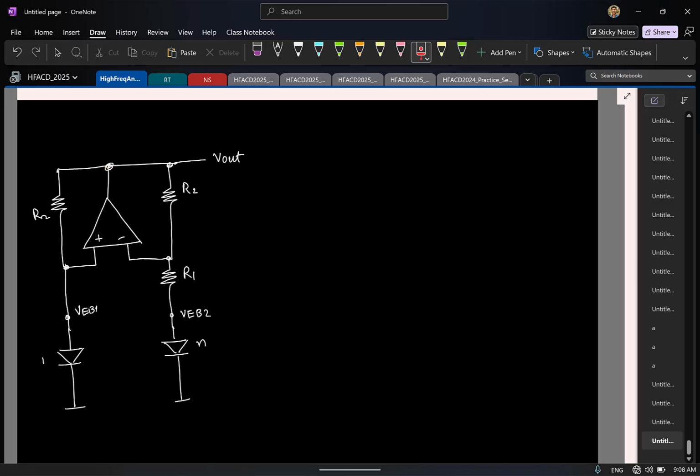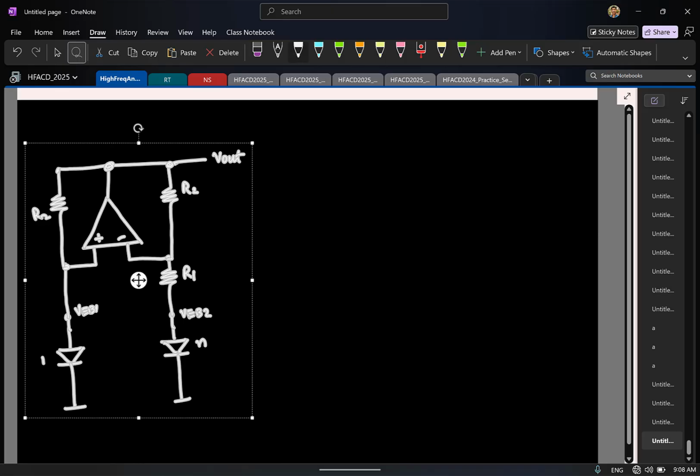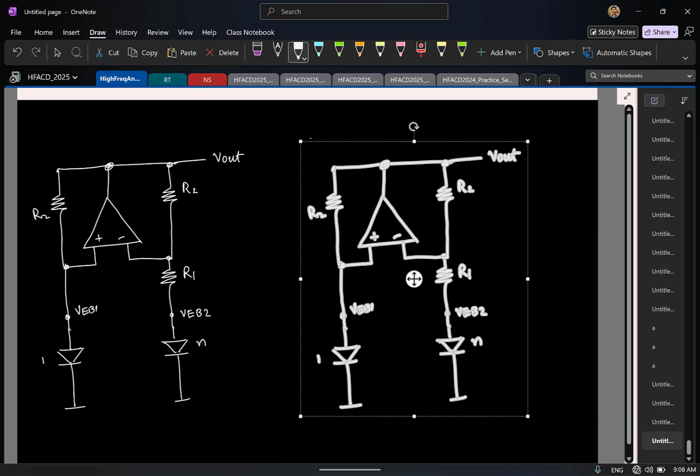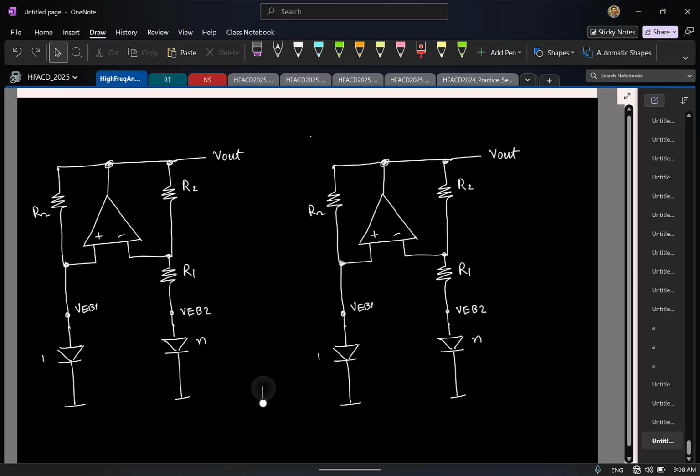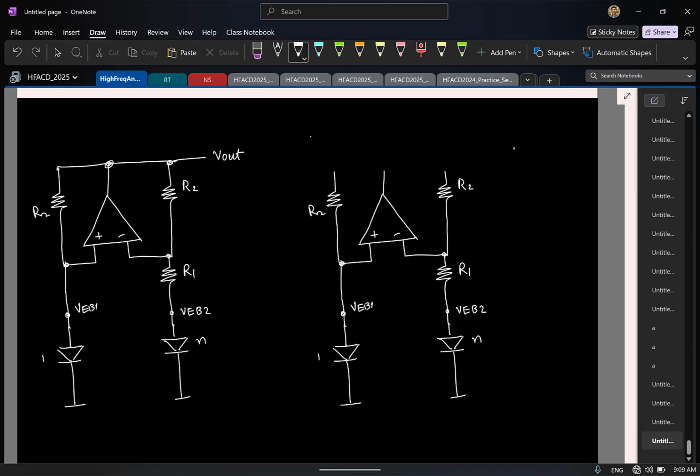Now you see that the output you are directly connecting to resistors. So the small signal gain will be loaded by the resistor branch here. So what can you suggest to do now? We can have a multi-stage structure, we can have a two-stage. So that's what is commonly done. So this is, as of now, the structure I have. Now I have to replace it with a two-stage op-amp. Which means this is no longer my output. Correct? From here I should have a second stage.